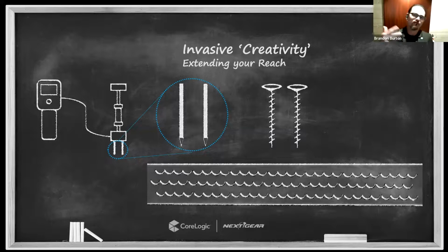So when you come back and measure, you just make contact with your electrodes right on the heads of those two seated screws. That's going to give you the wettest reading through the depth of that fastener, right? So that's the really simple form of doing this. But there are much more intricate ways of doing it.